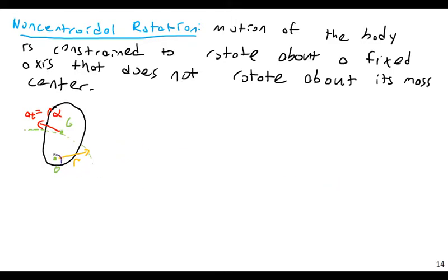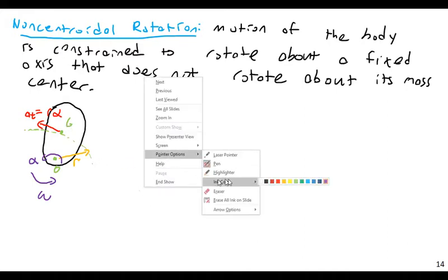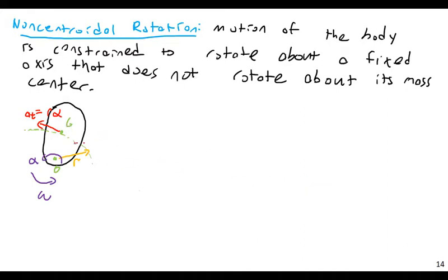So we have an alpha here, some angular acceleration, and also some omega, some sort of angular velocity. And the tangential acceleration is going to be r times alpha. You've seen this 1,000 times. And then the normal, or the centripetal acceleration, is going to be R omega squared.